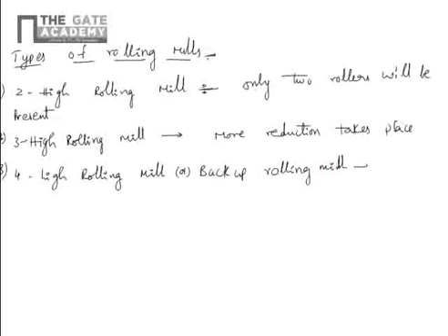As we have discussed, roller separating force can be reduced by reducing the roller diameter. So here we use smaller rollers such that the force generated or stress developed will be less. If you use smaller rollers, we need to use a small shaft, and there is a possibility of breaking the shaft. To avoid that, we use supporting rollers. This is the layout diagram: a small roller here, and a supporting roller. To support this roller, we use another big roller.